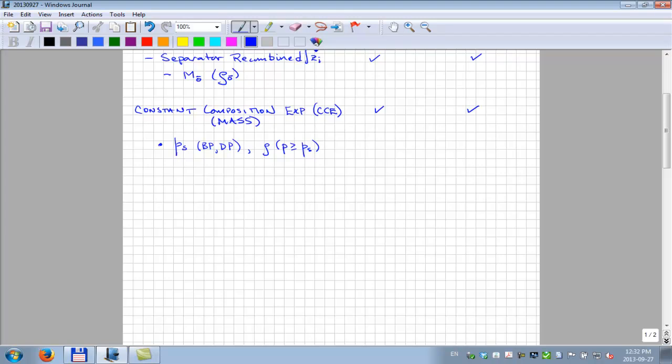Okay, so this saturation pressure will be at the reservoir temperature. In fact, all of these will be typically at the reservoir temperature. I'm going to draw this a little bit different. You may, in a seldom situation, ask for the same experiment at lower temperatures also. Maybe 100 degrees Fahrenheit, 30 degrees C, something like that. But it's not so common. But you may also ask for temperatures less than the reservoir temperature.